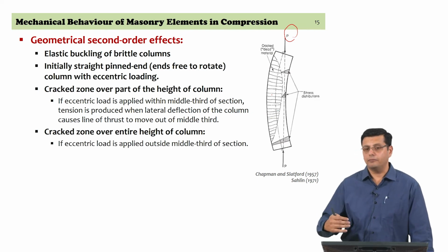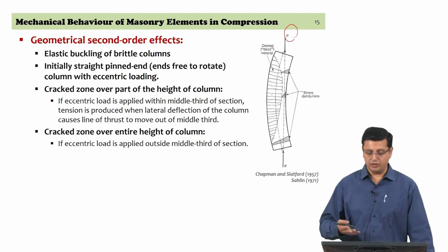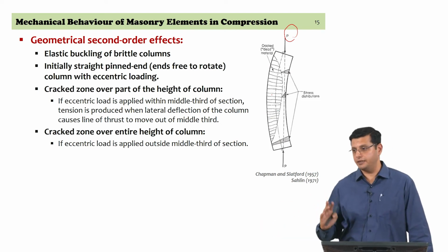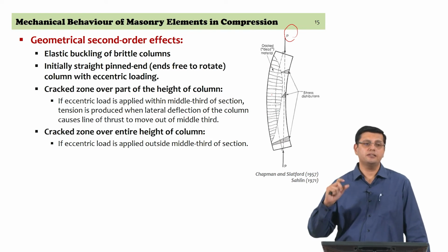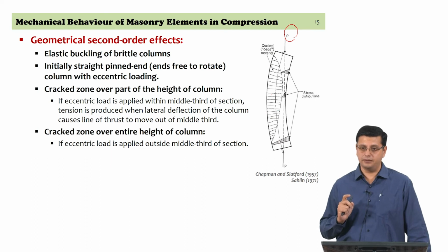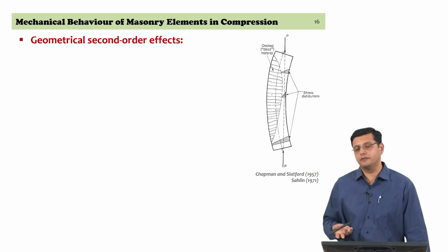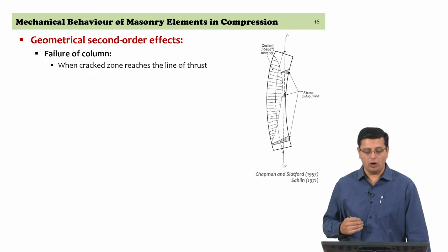So, basically you need to account for the fact that part of your wall based on your calculations should have cracked, and part of the wall may be in the uncracked condition, which means you have now different cross sections to deal with as far as load equilibrium is concerned, right. So, we will keep that in mind and use that as the fundamental difference between different resisting sections of the wall itself.